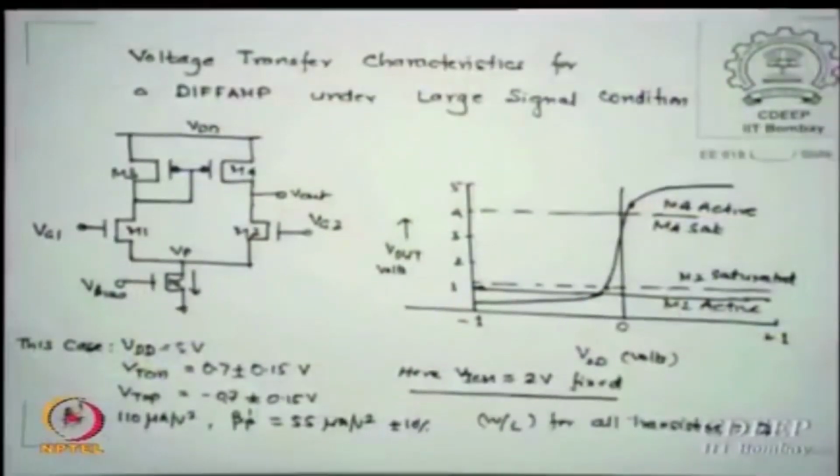We want to see the limits. So these are called limits or ranges. Two ranges of interest to me: one is at the input, the other is at the output. The output voltage maximum to minimum that I can get is called the output swing.